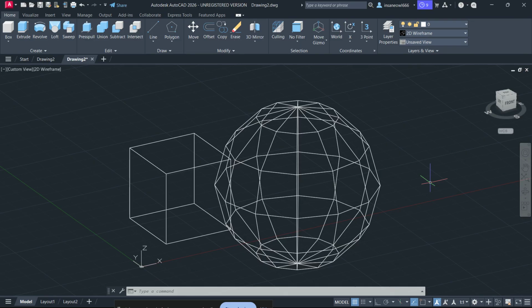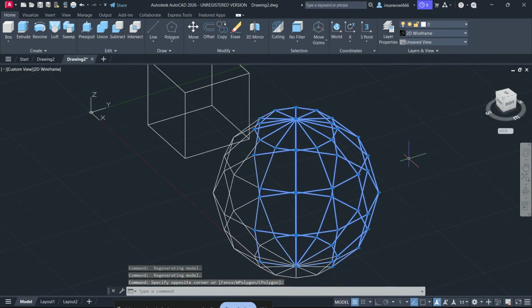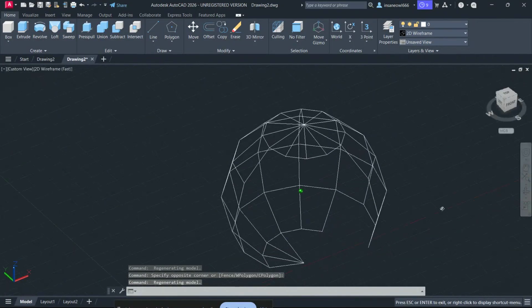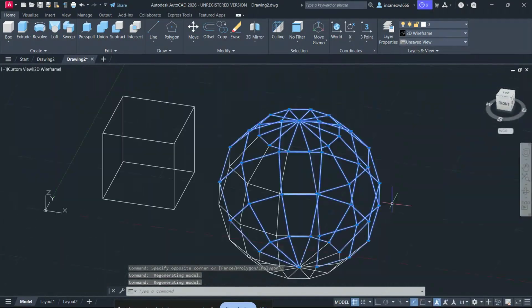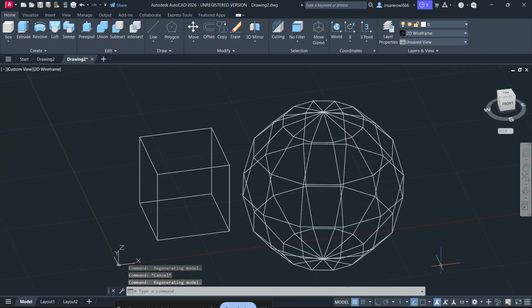First, let's understand why error 18030 happens. One common cause is coincident faces, which means two surfaces are sitting exactly on top of each other. Another cause is non-manifold topology, where the operation would create an impossible shape, like solids sharing a zero-thickness edge. A third cause is inconsistent normals, which often happens after mirroring objects or converting complex surfaces into solids. So the main goal is to clean up the geometry and make the model easier for AutoCAD to calculate.